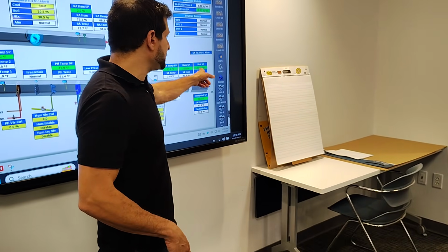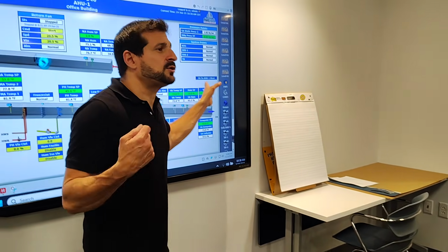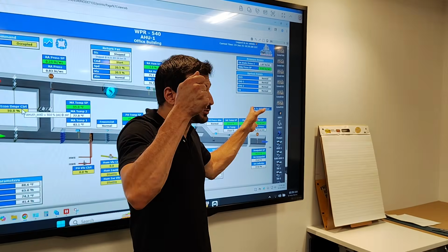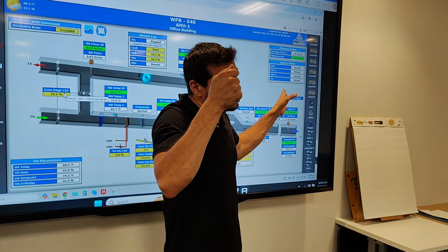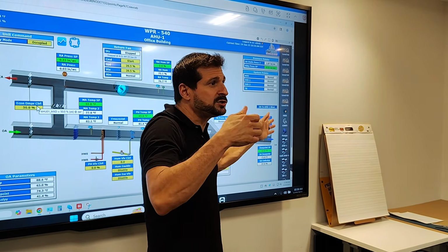What I would do is set this thing to a number, and it doesn't matter what it is, call it 1 inch, set it to 1 inch. Then I'd go down to your lowest floor and I'd measure the pressure in the duct with a magnehelic. And I'd see, am I only at a 1/2 inch down here? Well, then 1 inch is not enough. And I'd bring it up a little bit. And I would do it until I get that number.